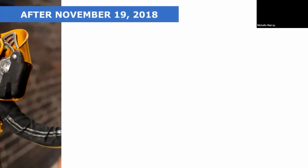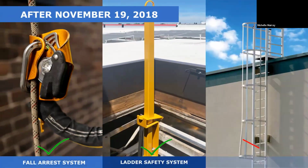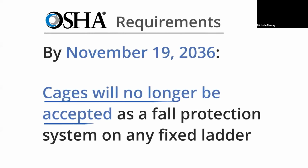Fixed ladders installed on or after November 19, 2018 must be equipped with a personal fall arrest system or a ladder safety system. Cages are not permissible as a means of fall protection for newly installed or replacement fixed ladders. By November 19, 2036, cages will no longer be accepted as a fall protection system on any fixed ladder. So just to reiterate, today, if the fixed ladder is under 24 feet, a cage still can be used as fall protection. But after November 19th, 2036, cages will no longer be accepted as fall protection on any fixed ladder.